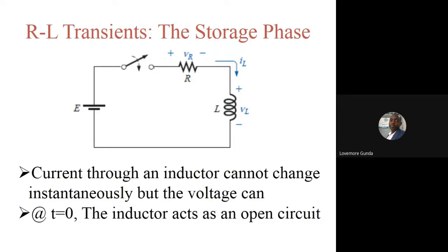So this is an example circuit which we can use. We close this circuit and try to push a current, and there is an opposing voltage there, so this is initially open. Then as the field collapses, the voltage decreases and current starts flowing in the circuit until it reaches a maximum, when this is now equivalent to a short circuit.